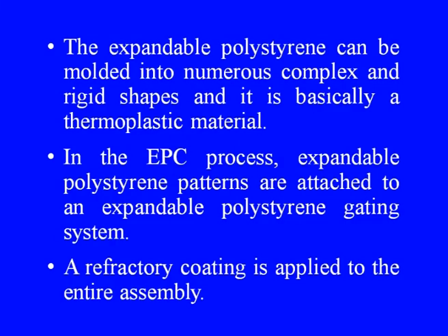The expandable polystyrene can be molded into numerous complex and rigid shapes, and it is basically a thermoplastic material. In the EPC process, expandable polystyrene patterns are attached to an expandable polystyrene gating system.